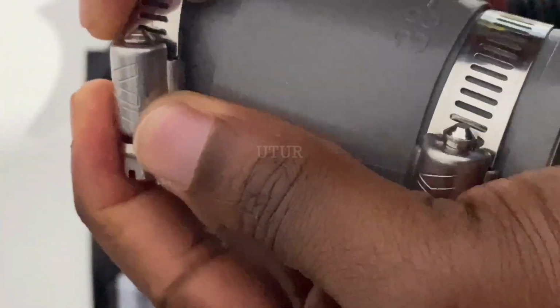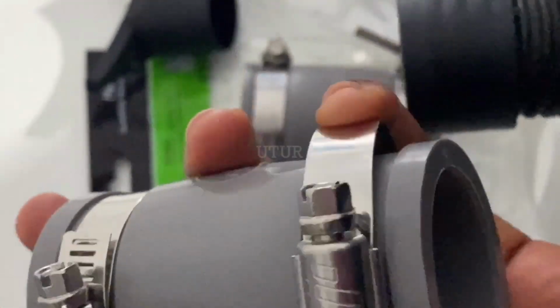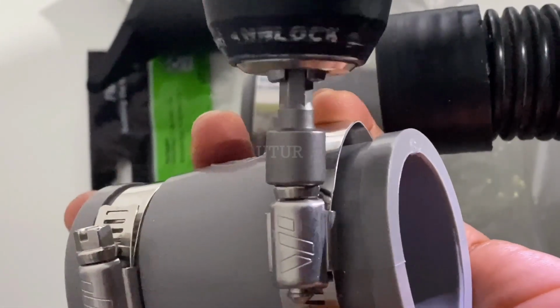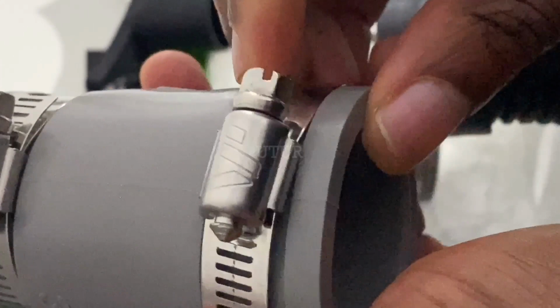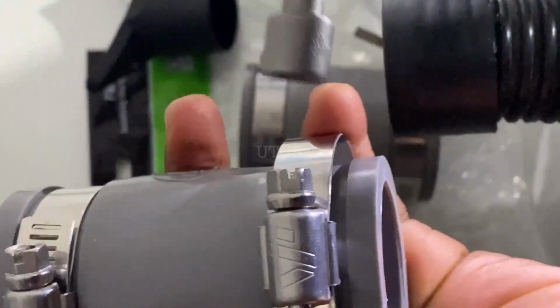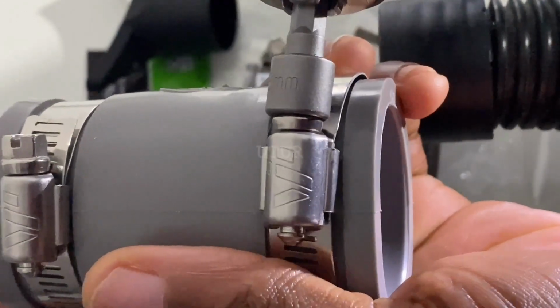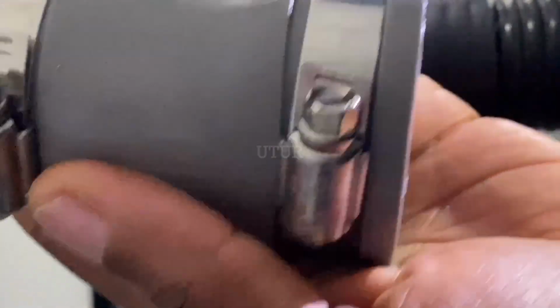The best way to do it is just to set the step clip first into position, then start torque tightening it back so that it latches onto the teeth of the step clip incrementally as you torque tighten. And so basically, when the arrow on the drill faces down, we're torque tightening, and when the arrow faces up, we're torque loosening. Okay. And here you can see that the clip teeth have started latching onto the other mating pad from the other end.